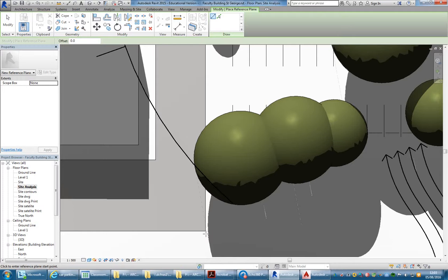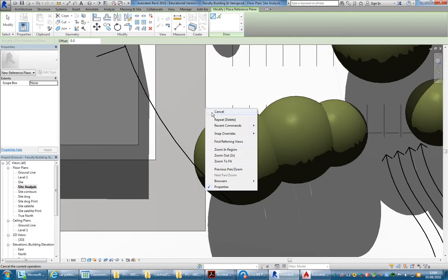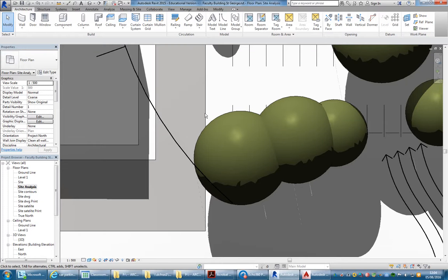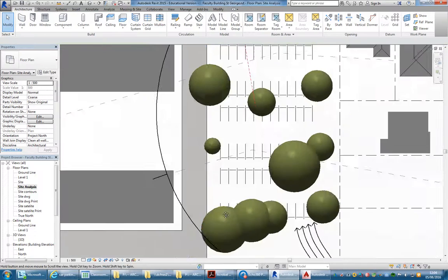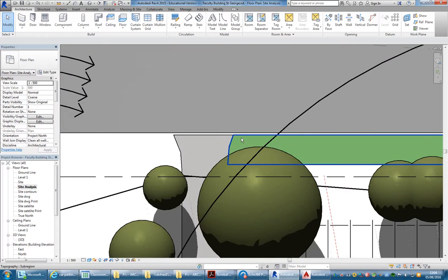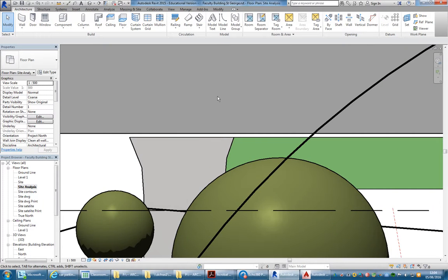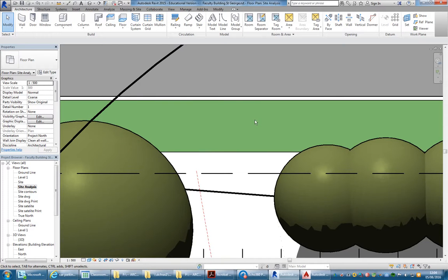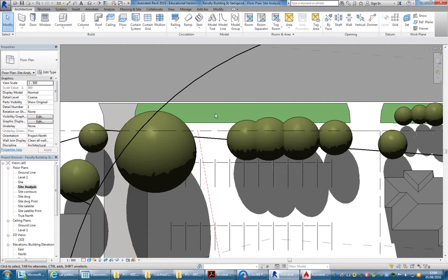It's one of those frustrating things in Revit. So if you just draw a sub-region straight up on your topo surfaces, you'll face lots of issues like that. They're difficult to manage and really difficult to work with when you want things to be accurate. Later, when you start putting in lots of different sub-regions, you'll need to put in a gutter between your road and, say, your verge, and snapping to those edges is really difficult. So, don't worry, if you have to, you can. There is a way, but it's just not easy.